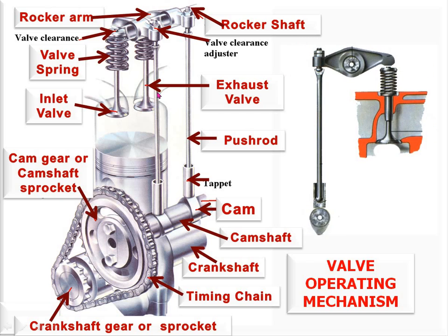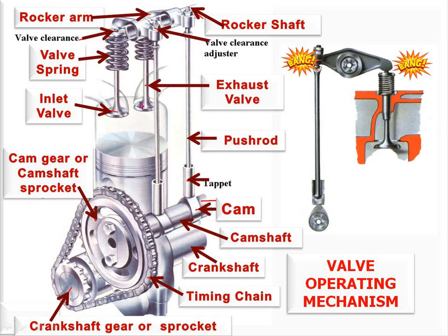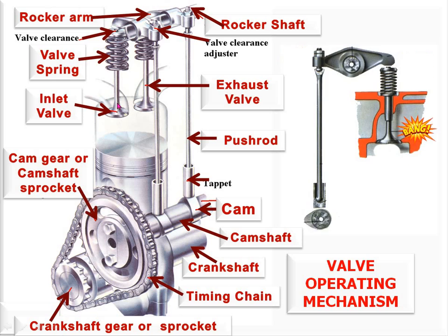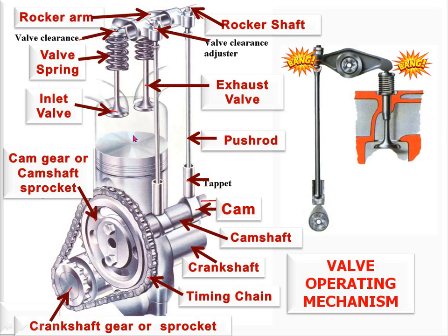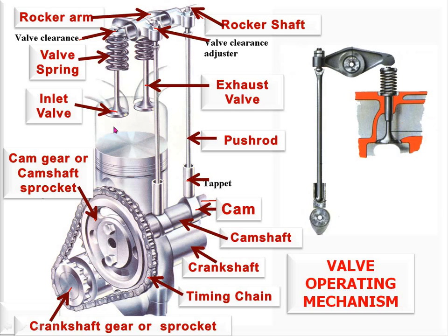So if it is the inlet valve, then at the time of the suction stroke, this valve pushes inward, so this opens the hole, and fresh air comes through the inlet into the cylinder. After the power stroke, during the exhaust stroke, burnt gases must go out of the cylinder.